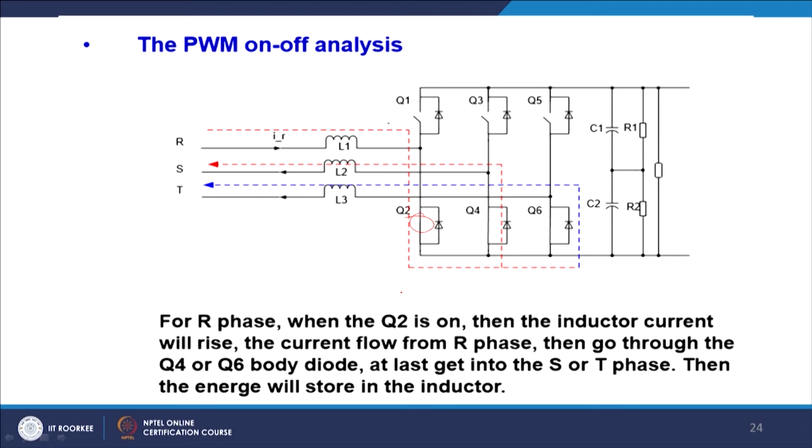So, you can have the logic that the lower switches are closed, and this is closed, and this is closed. So, this is essentially the state in space vector modulation as 0 0 0. That is what we have considered, and in that case this gives you the boost mode of operation.